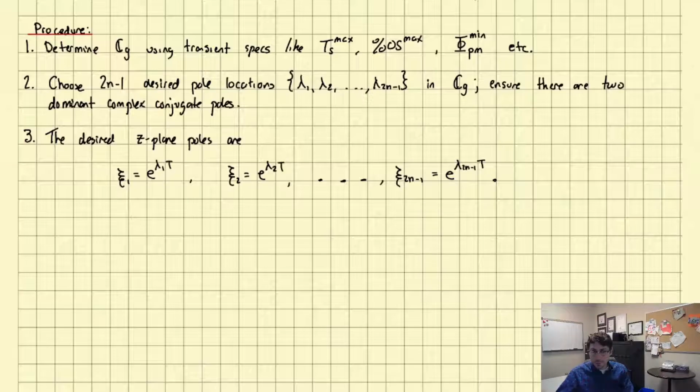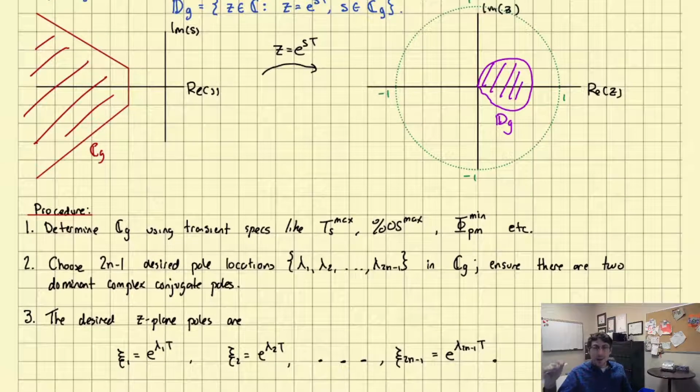Okay, so I'm going to stop there. The takeaway message here is that, as long as we're careful about discretizing our plant and picking reasonably good sampling periods, we are then going to treat it like a discrete time system. And the first design method we've talked about is pole placement. The good news, or maybe bad news, depending on your point of view, is that it's exactly the same. In some ways, we've reviewed Chapter 3 material. The only difference is that when you pick the pole locations, we use this procedure here. A slight difference in the way you pick the pole locations, but the equations you solve, the structure of the controller, everything is the same.